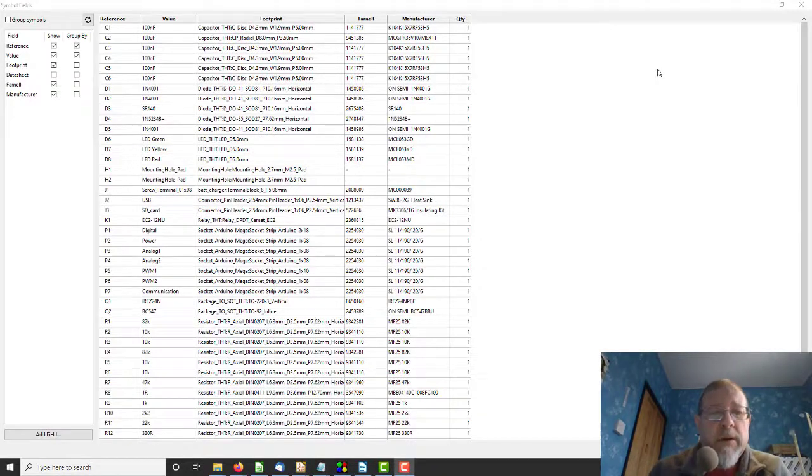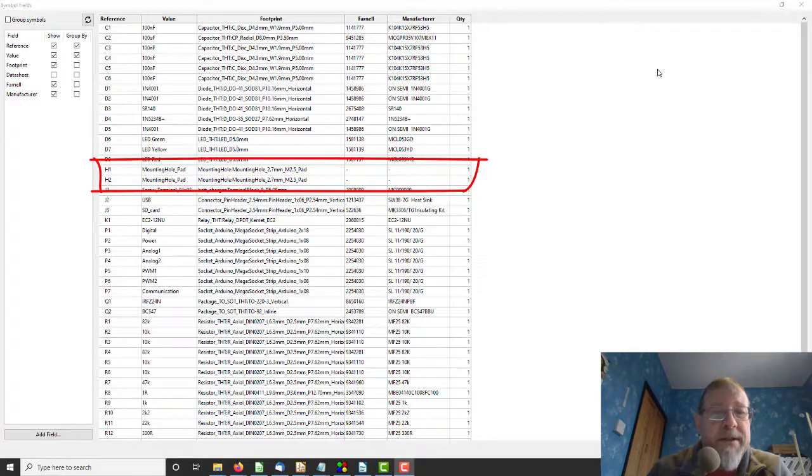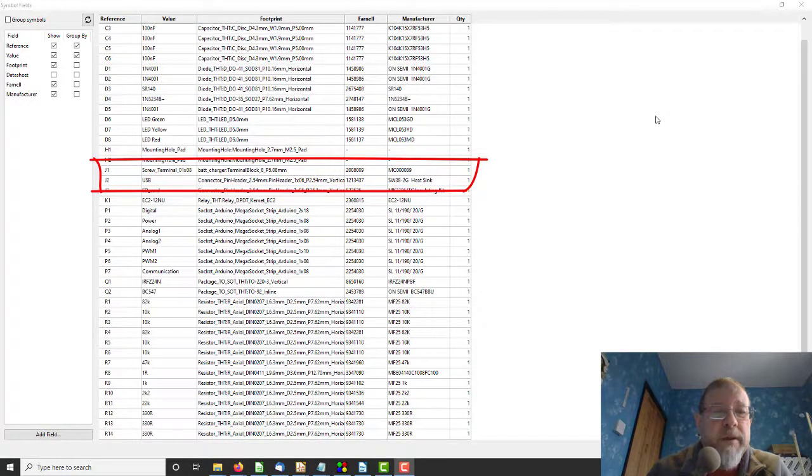So here we are, we're all done. A couple of things. Now the heatsink has two little pins which go through the PCB and solder down to hold the heatsink to the PCB, so I should have made a component with those two pads on, but I didn't. I just used two pads and drew an outline, and those are the two pads.